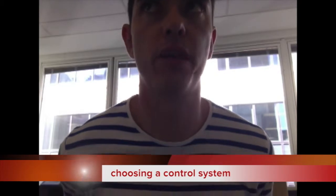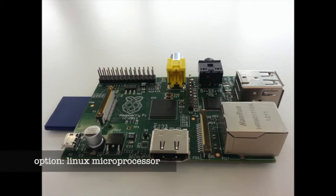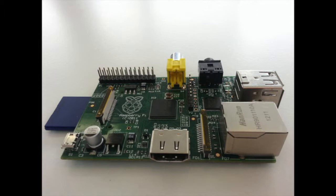The first choice we have is about deciding the control system, which would typically be a microcontroller. One option we have is we could use a Linux processor, such as that on a Raspberry Pi. The problem with a Raspberry Pi is it consumes a lot of power, around 700 milliamps, which is around 100 times what you would normally find on a microcontroller. Also, with Linux, at any time the operating system may switch out your quadcopter process. That makes it highly unlikely that it will run the 400 loops necessary to keep in the air.